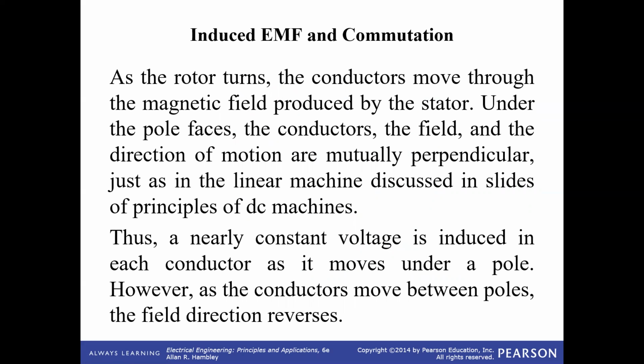And induced EMF. So what is induced EMF? If you notice, a machine that rotates will produce what we call back EMF. This is a voltage that is proportional to the speed. So if you increase the speed, the voltage induced inside the motor will also increase.